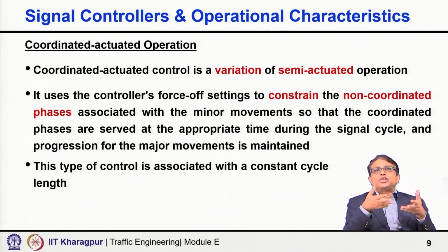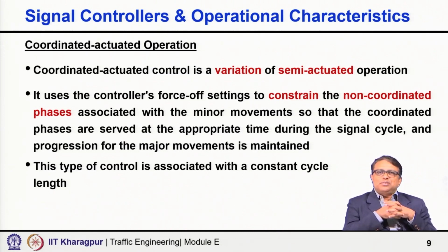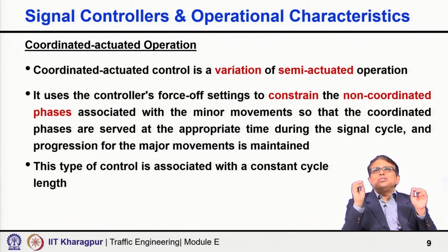Then coordinated actuated operation. It is something interesting and it is a kind of variation of semi actuated operation. That means, the minor approaches are actually actuated, or we are doing detection there, and those are the phases which are actuated.